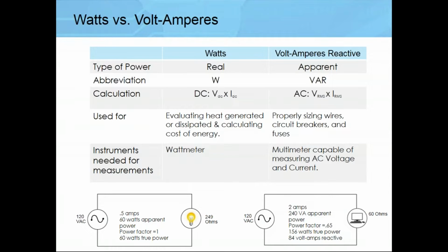The total power required is a combination of watts that are required and the apparent power that is required in terms of VA. So if you ever see power requirements that are listed in VA, you know that this component has some kind of resistive element, some kind of capacitive or inductive element, which will allow it to have a rating for voltage times ampere. If you have just a purely resistive load, you're going to see watts listed on it.